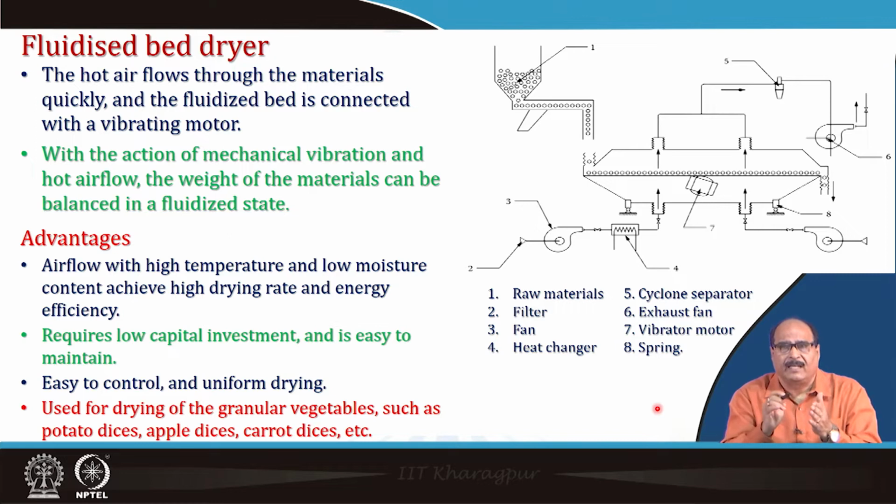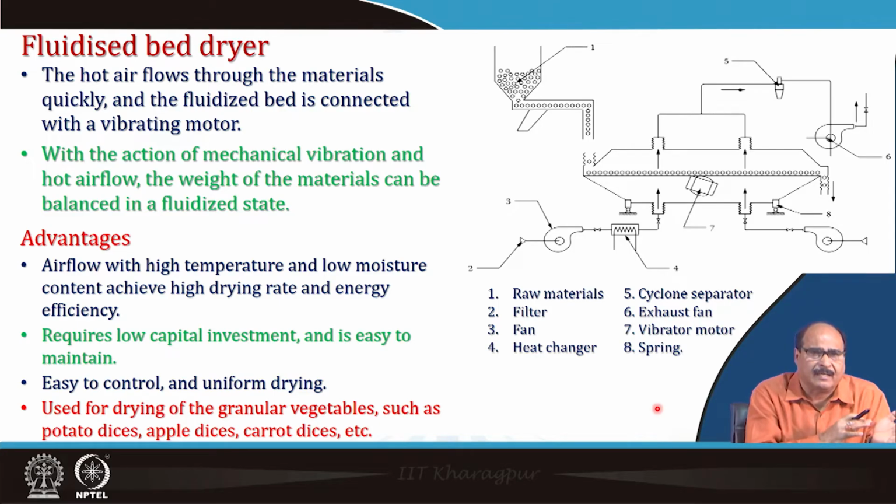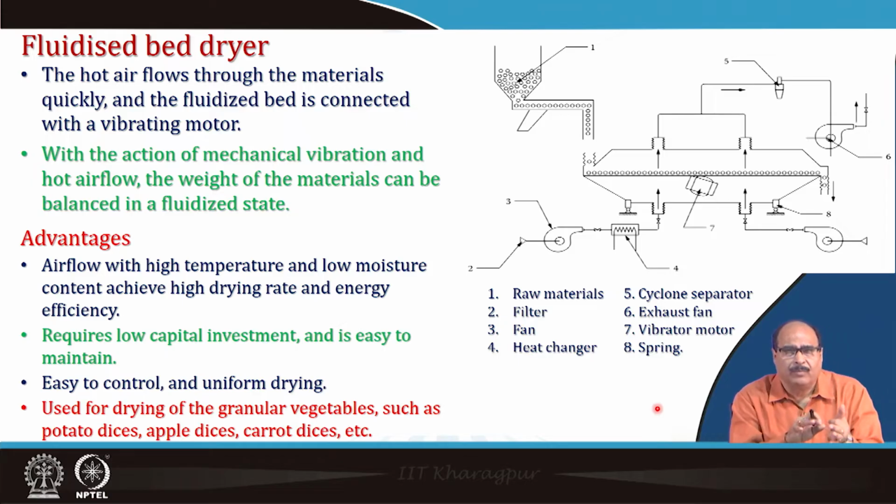So basically this is a little advancement of hot air drying, where the material is kept in the fluidization state, and the advantage of this system is that airflow with high temperature and low moisture content achieves high drying rate and energy efficiency. And also it requires low capital investment and is easy to maintain, easy to control, and gives uniform drying, because the material is fluidized, so heat transfer is increased.